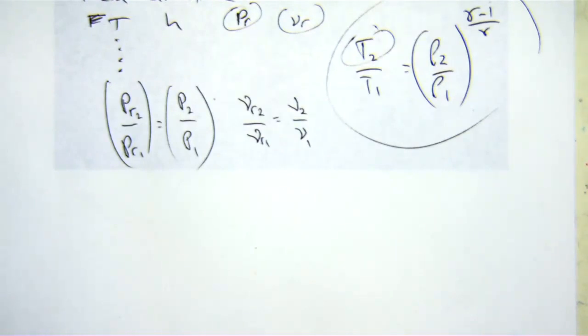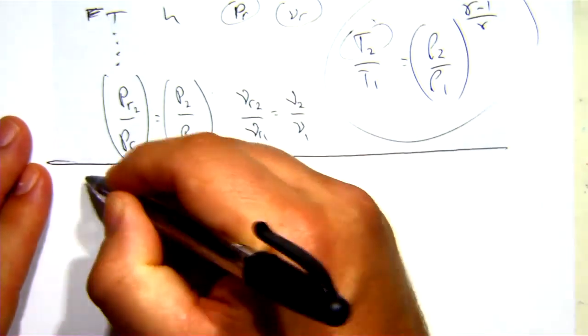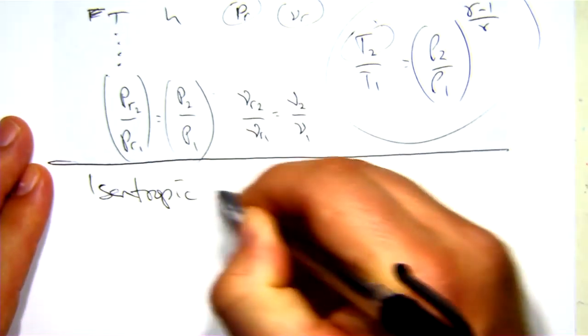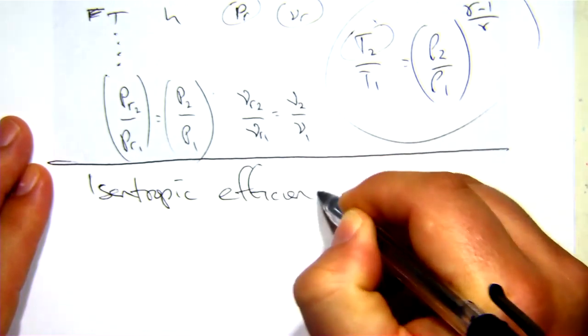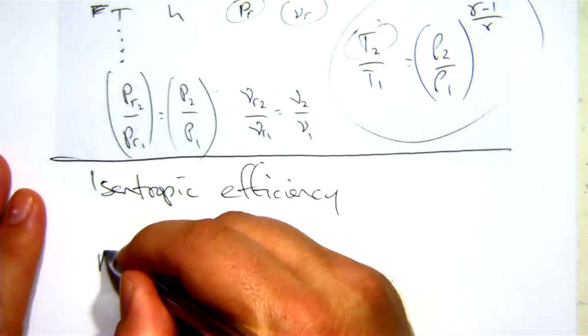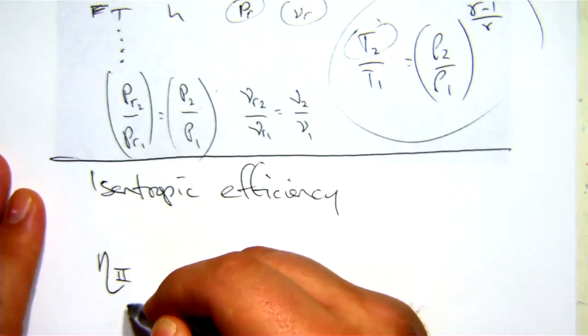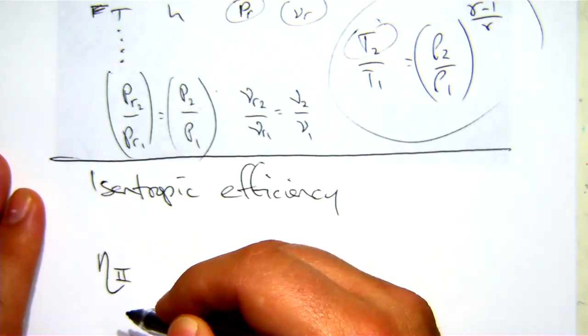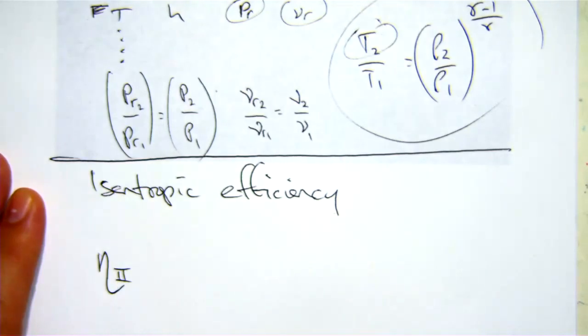But for a component, we refer to the isentropic efficiency, which is the actual output divided by the best possible output if it's doing work, or, so the efficiency has to be less than 100, right? So the ratio, if I'm doing a compressor, the notation for it is a 2 for the second law. Okay, so it's referring to the second law in entropy.